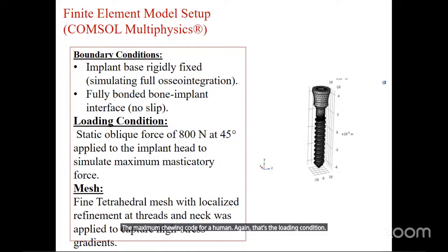After assigning all the boundaries, you will now do what is called meshing. In the interface we are going to see meshing, and the meshing normally goes from coarse meshing to extreme fine meshing. Coarse meshing means dividing the design into individual parts, so that the software, COMSOL, will be able to calculate at every point of the design. If you do an extreme meshing, depending on the computer you are using, you might find the simulation takes longer, or does not even finish.